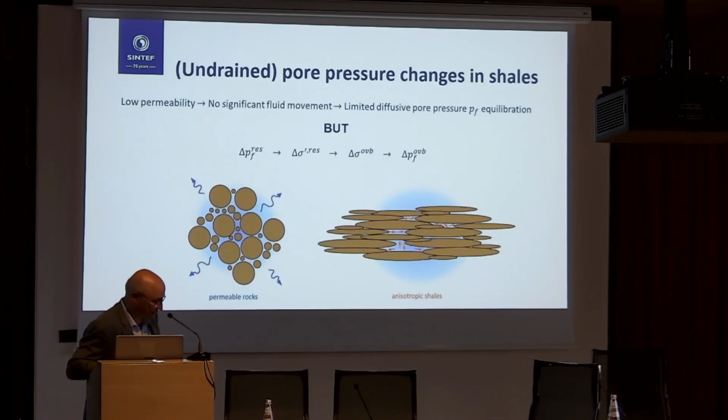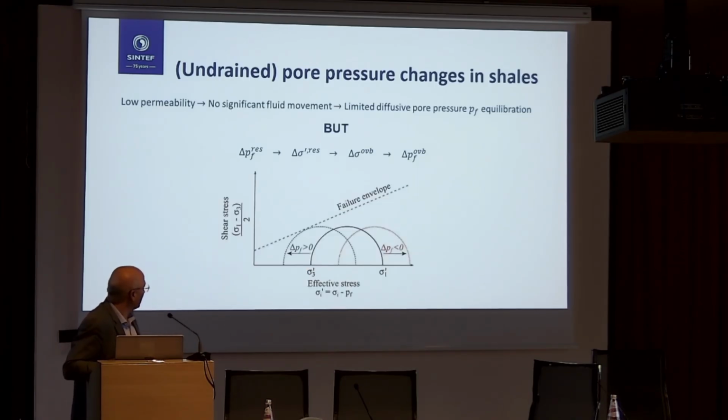Now, a further complication is that, as you see in this cartoon, shales especially have an internal or intrinsic structure, or anisotropy, which further complicates things. It doesn't just inflate like a balloon, which we assume a lot of times in our models. You'll see that there are some preferential directions, and this has an effect when we try to answer which of the stress components is impacted by what.